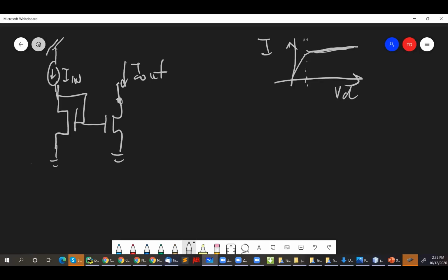Okay, so first of all, because it's an input current coming in, something has to set the gate voltage. So you cannot do this. Sometimes people draw a circuit and then they draw this. This circuit should look funny to you. Because it's true, you have an input current, and you can say the gate is tied to something, it's not floating. But the thing is, nobody's driving the gate. So how is this voltage here set?